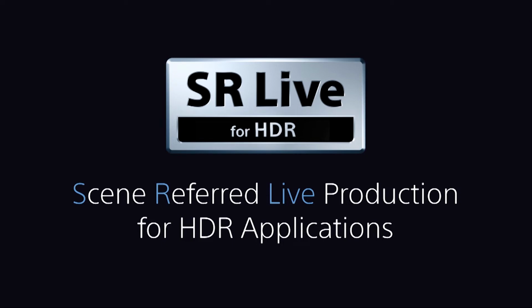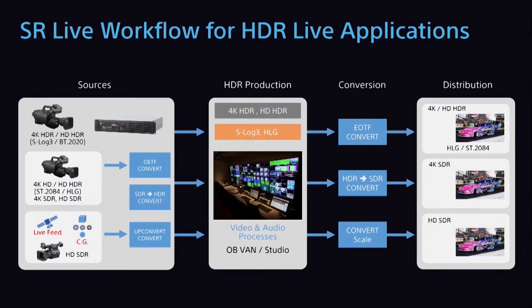The Sony ecosystem is called SR Live. SR means scene referred, as seen by the camera. All the production is based on processing signals created by capturing the light. This is a typical production environment, whether it's for a studio or for outside broadcasting. The center portion is the production environment. It has to be 1080 progressive or 4K in color space 2020. And Sony has selected in our product S-Log3 or HLG in production.